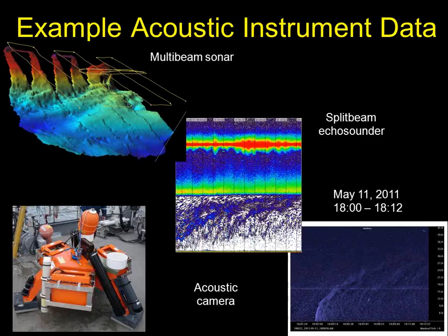In the lower right-hand corner, we have a coincident echogram from the DIDSON, and you can see in both the middle and lower images a plume event that's coming up off the bottom during that 12 minutes, probably silt moving up. From the echo sounder you have to know where to look, but there's some avoidance of that plume, as you can see near the lower left portion of that slide. The picture there is again the DIDSON. So we had the DIDSON, the Biosonics echo sounder, and the Reson multibeam all looking up in those packages on the bottom. Next slide, please.